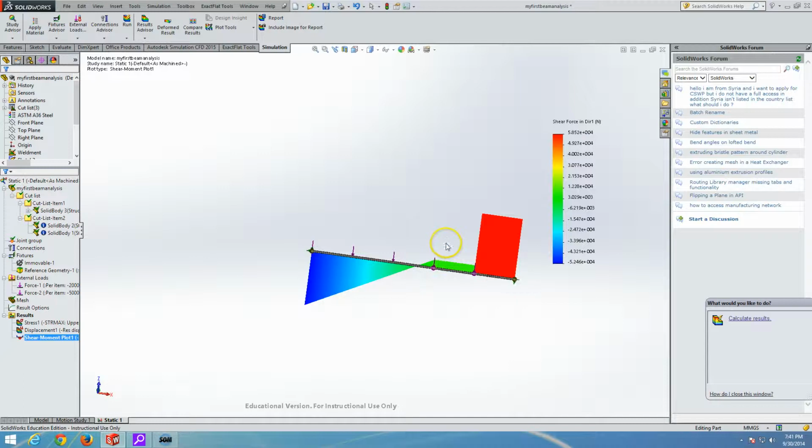So, and then we have our point force applied here. And if we do the sum of all vertical forces and sum of the moments around the point, we will see that this is actually a correct result. And is consistent with analytical. Now, remember approximately the position where this force was zero. It's here.